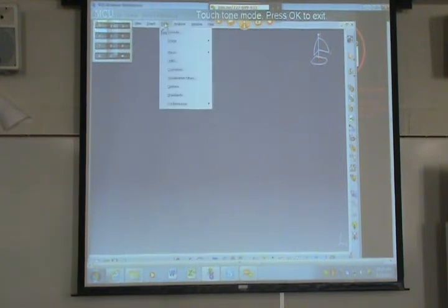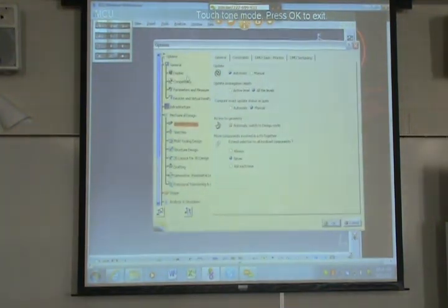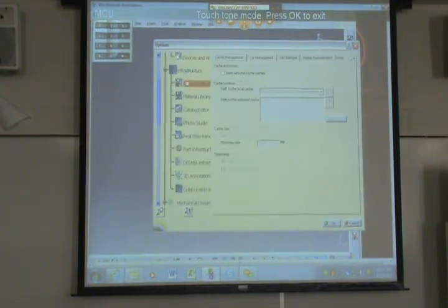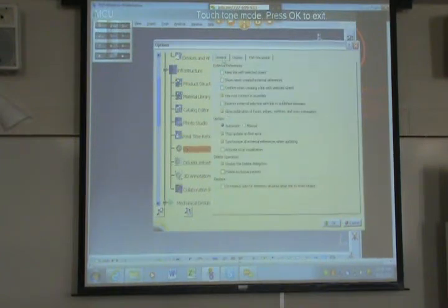So to turn that option on, go up to Tools, Options, and then inside of the part tree, you'll go to Infrastructure, and you'll come down here to Part Infrastructure. And then underneath the General tab, there is a Keep Link with Selected Object. That has to be turned on for top-down assembly. Anything that you create while this link is turned off will break the links that allow that morphing capability. Okay, so that has to be turned on.